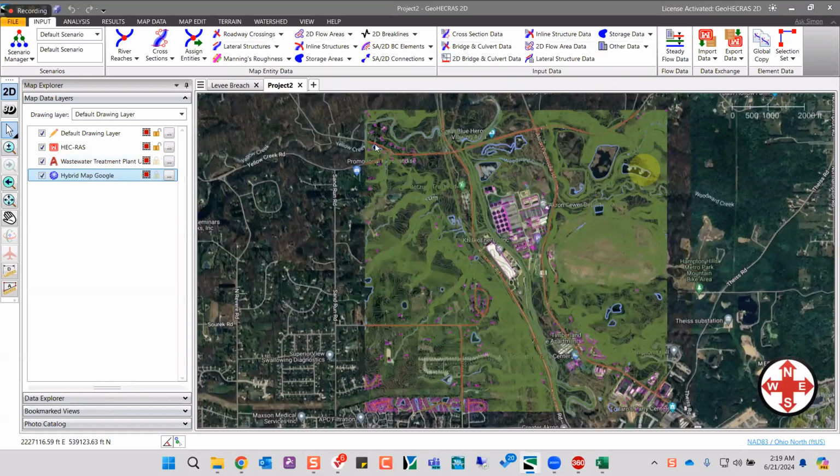It overlaps perfectly here, right? The reason is when we loaded this CAD drawing file, the software automatically picked up the coordinate reference system that was associated with this CAD file, and it assigned that as our current model's projection, which you can see here at the bottom right.